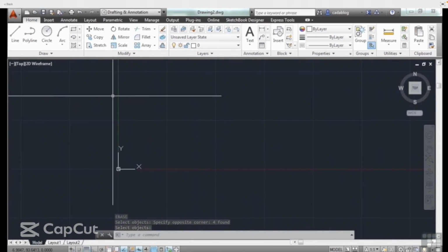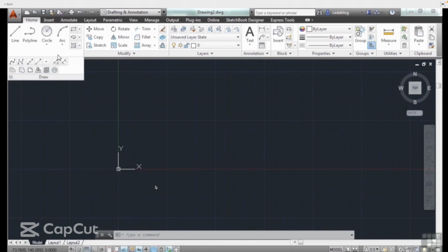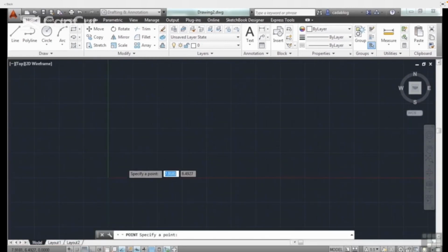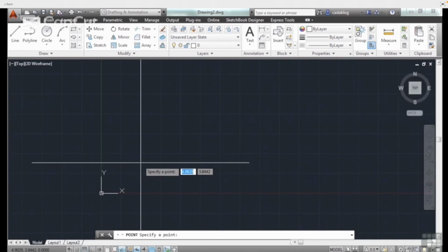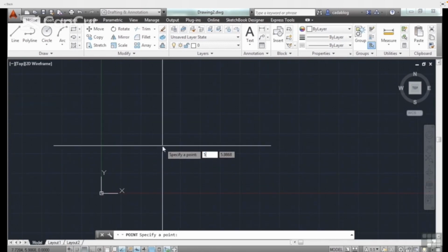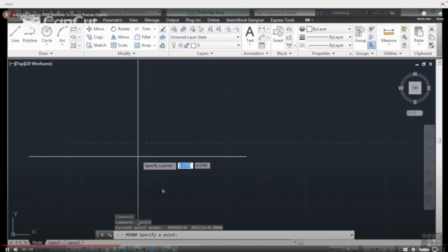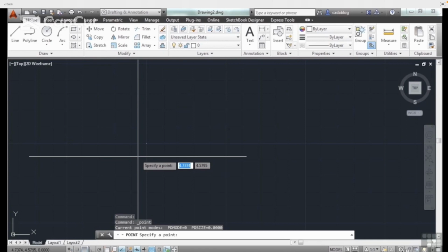Now let's put a point in at a specific coordinate. Start the point command, and then let's zoom down here a little bit. So type in the number 5, the tab key, and the 5. So this will put us at coordinate 5, 5, right here. Points are also three-dimensional, but not in AutoCAD LT, just like every object in AutoCAD. If you leave the third coordinate off, it will be drawn at an elevation of 0.